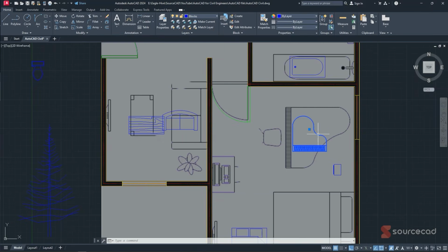So for this one, we need to rotate, select RO rotate, hit enter, specify the base point being any point, let's say around there, select on it, move it up to around this point where we can see the keys aligning, then move it again all the way up, place it there. So we're going to simply use scale.